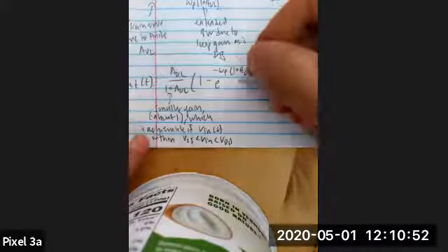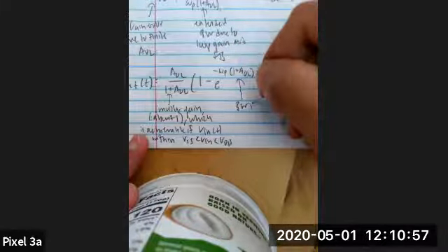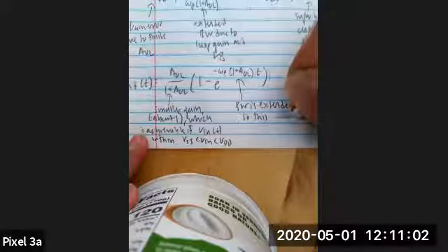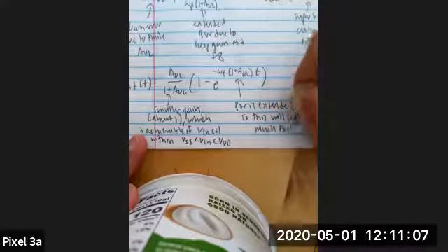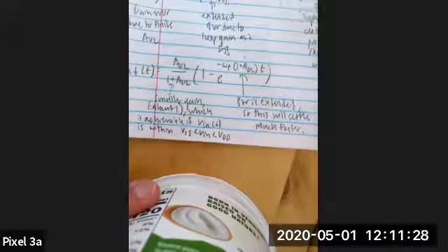And then we also see that this time constant is going to be, this bandwidth is extended. So this will settle much faster. And that's really how this closed loop feedback has saved our response, because in the first case we had a really slow settling and an unachievable gain, and now we have an achievable gain with much faster settling, especially if A open loop is high.